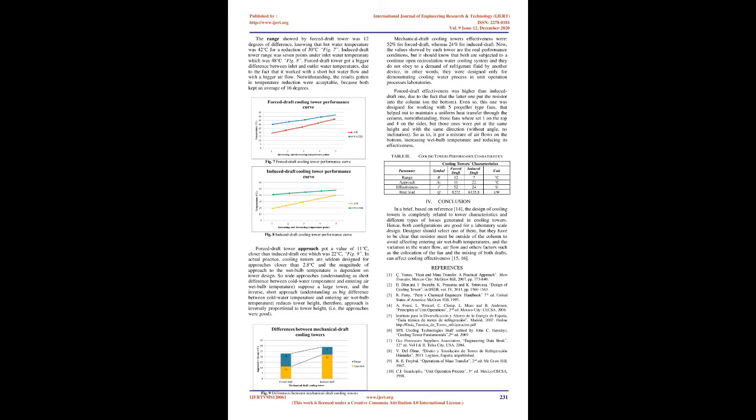Equation 2 is the approach to wet bulb temperature, AC, the difference between the cold water temperature, TL1, and the atmosphere wet bulb temperature, TWB1, in degree C. It is the most important factor in the tower performance. A short approach indicates high effectiveness, but high costs and energy consumption also. Tower height is inversely proportional to the approach. If the approach is small, height is high, and vice versa.